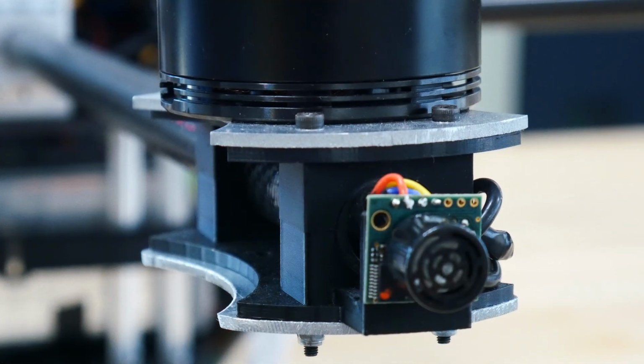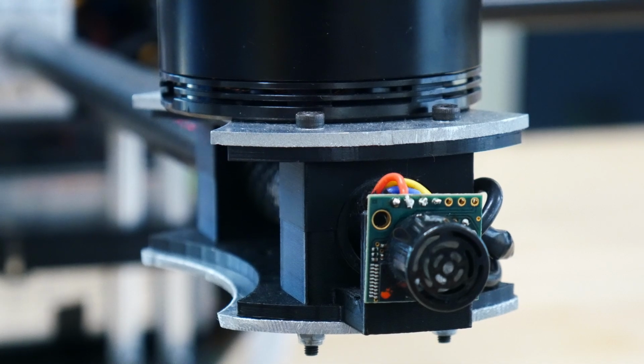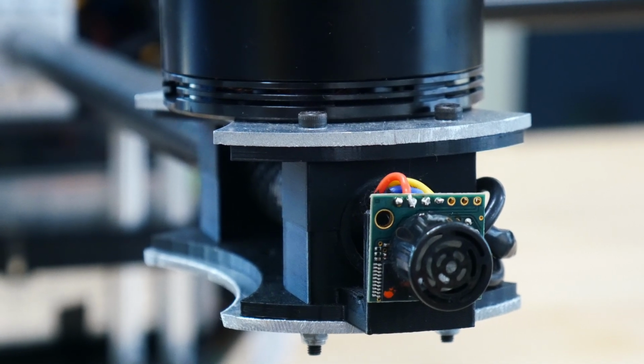For obstacle avoidance, we utilize ultrasonic sonar sensors in order to detect other aircraft. These are relatively small hardware devices that we mount on the ends of each of our arms on our drone. Now, in terms of algorithms for obstacle avoidance, we can utilize some off-board commands to make some quick adjustments to the drone's position.